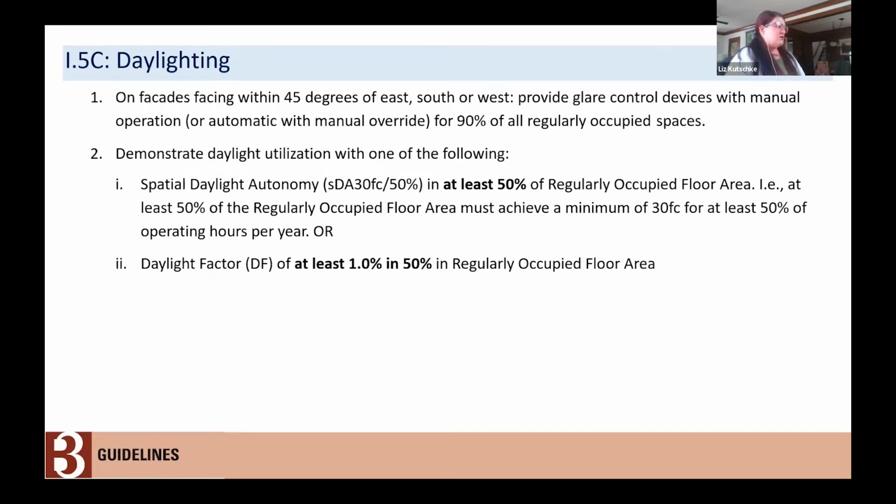And previously we had requested that the foot candle threshold be tied to the use of the space. So it was a little variable depending on the program in that space. And we have moved away from that complexity and moved to just the static 30 foot candles to move in line with programs like LEED and to reduce the effort that was required of project teams that we didn't see much of a benefit to on the reporting side.